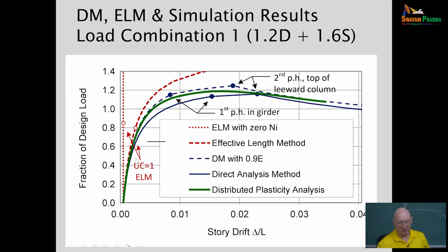And so what do we have going on here? Basically, load versus lateral deflection. It's just a gravity load, but we're approaching a situation where, when we ran this with the reduced elastic stiffness, we're getting very close to a buckling load based on that reduced stiffness. So it's starting to deflect a lot. That's what the direct analysis method or these other notional load-based approaches in Eurocode are relying on. If we're not going to base our column stability on buckling analysis, we're basing it on a geometric nonlinear load deflection solution.